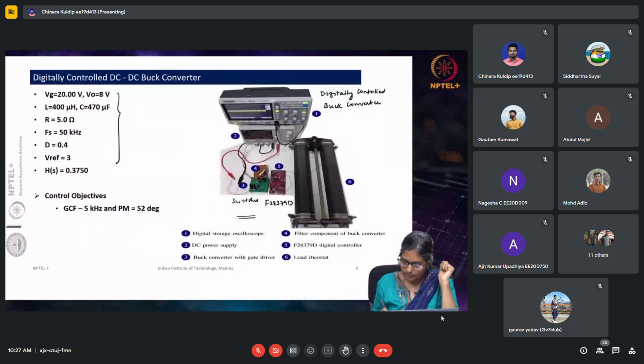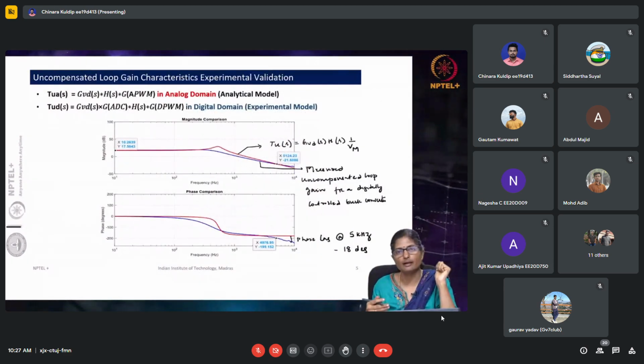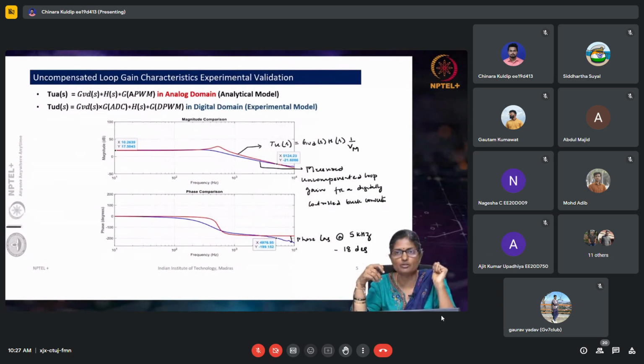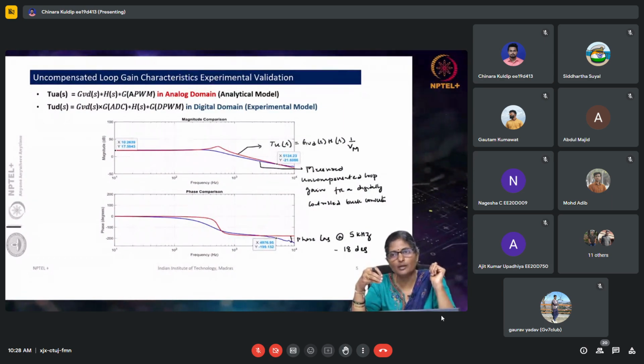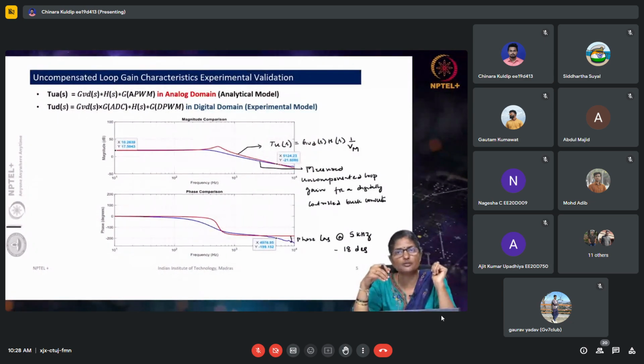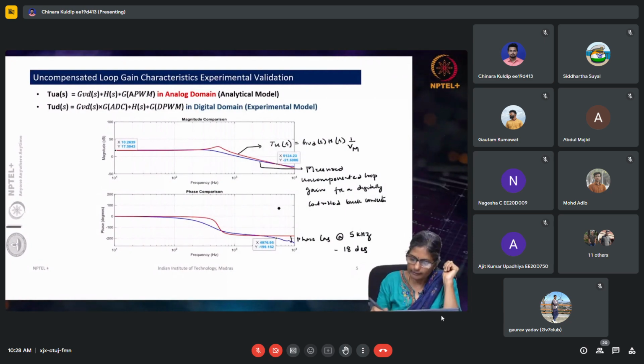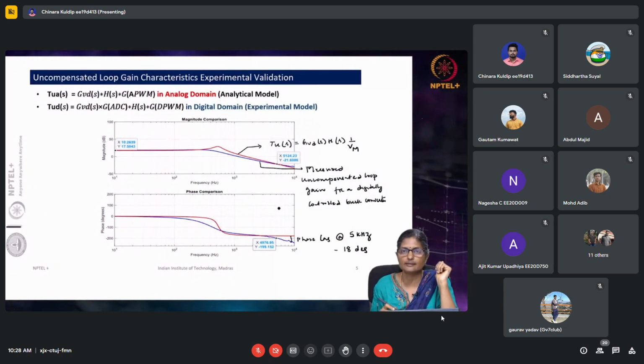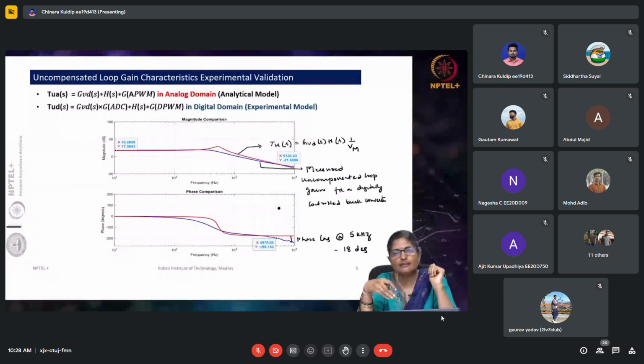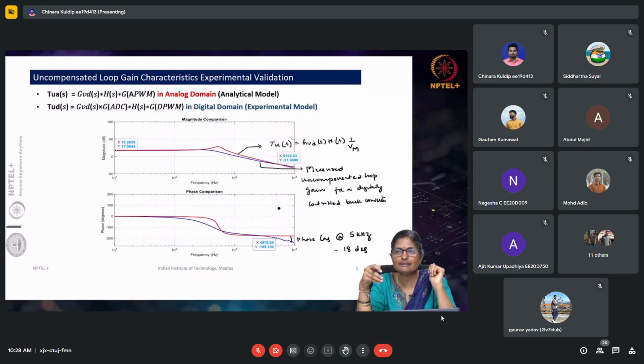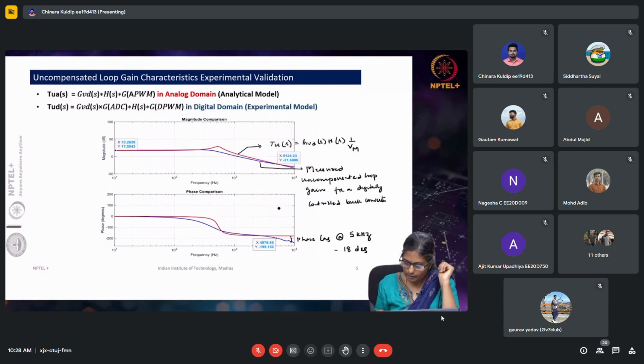The same is observed in the hardware implementation also, and these measurements and validation of course enable us to model the plant accurately and then do an accurate controller design. To obtain the frequency response characteristics, something like what we are seeing in this picture, one could use an instrument, the frequency response analyzer, right. So, that is one way.